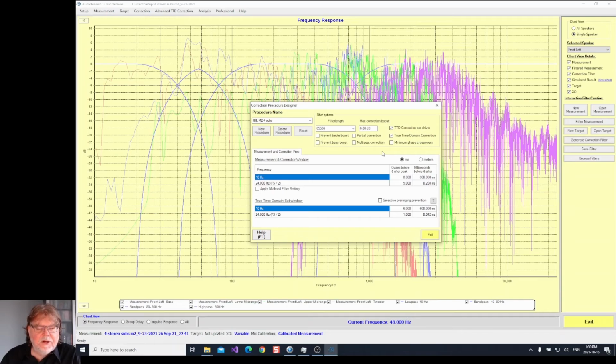Now we've got a pretty decent sounding speaker, but there's room for improvement in how the drivers collaborate. The process that was done on a per driver basis is now repeated on a per speaker basis. So AudioLens simulates the response for the whole speaker based on per driver correction. We analyze the psychoacoustic frequency response of this and perform a global frequency correction and a global time domain correction.